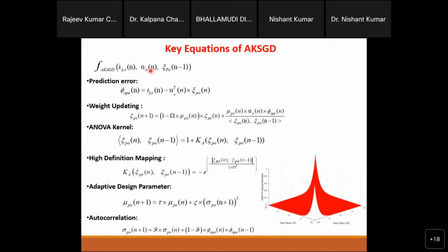So the issue is that the PLL is tuned for a particular error. Once your error is changing or deviating, the PI will need to retune, right? If you do not tune it, then it will still work, but it will take a longer time to converge or settle down on a steady state value, right? But in this situation, we will not use PLL. In place of PLL, we can use this unit template concept. I will discuss what this unit template concept is, and what this unit template is.